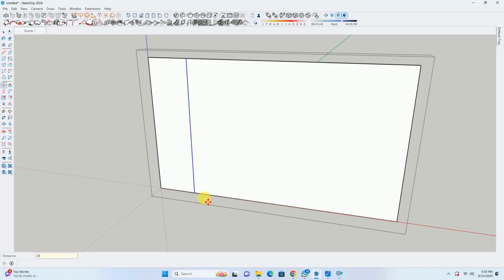Once I have copied an element, I'll press the X command and type in the value 4 and hit enter. So you can see that we have copied this line 4 times, but some segments are still remaining. So I will again press X and type the value 6. Now you can clearly see we have created 6 segments on the surface, right?